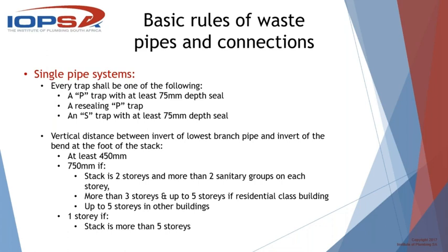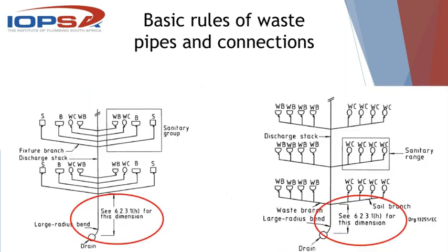Create another stack or a separate set of gullies and soil discharges for the first floor, and the second, third, fourth, and fifth, etc. floors will have a common stack. But don't join the first floor's wastewater to that stack. And we all know the reason for that, because there's a possibility of blockage down the line, and because of the amount of flow through that stack, we can have severe, and it's not even flooding, it's sewer flooding in the lower, in the first floor.